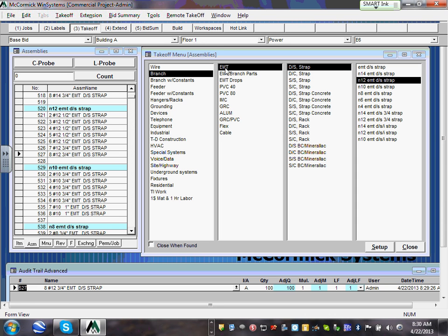Okay, how are we going to take this building, guys? Because I have to tell you what type of wiring methods we'll use when you take off this building. So Joe, we're going to be taking EMT conduits in the roof, in the ceiling for home runs. Inside the walls, for receptacles and for lights, when you tie to the lights, we're going to be using MC cable. Did you guys hear me?